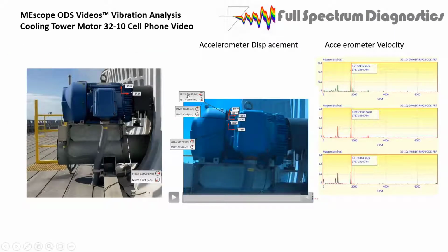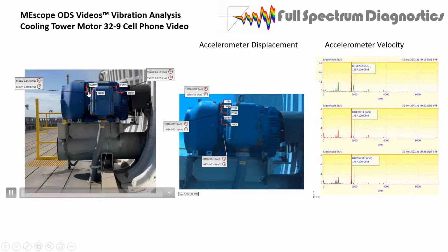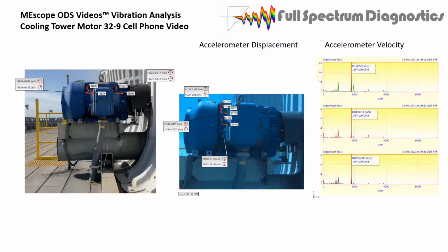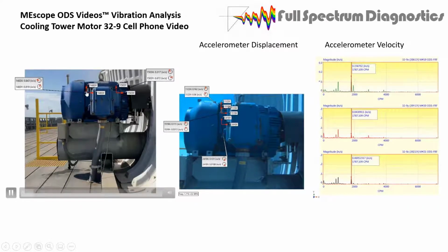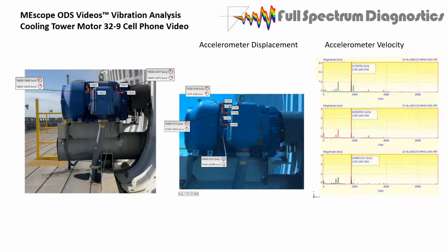Yeah, the mag phase display tells you, for a given point, something like this. Usually my transducer is going to be somewhere right here on either side, for detecting bearing faults. We can pull up labels on the point that I select that's closest to where the transducer was measuring, and it'll give me a location, what direction it is, and what the amplitude level is, and then it'll give me a phase difference between that and a reference point. In this case, it's just showing me its own reference, which is about 90 degrees. But if I assign it to another point and ask what the phase difference is from here to here, it'll tell me they're in phase or out of phase. It's just a quick look, kind of like a bubble chart when you're doing a manual phase analysis.